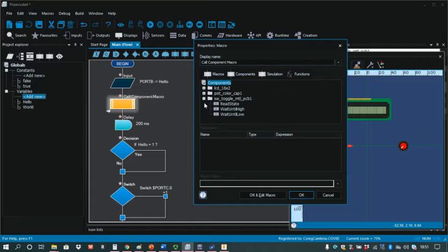So for the toggle switch, I can read its state, and it will tell me whether it's a 1 or a 0, and I can wait until it's high, and I can use it as an interrupt when it goes high, or an interrupt when it goes low. So those are pretty much the only options for a simple toggle switch.